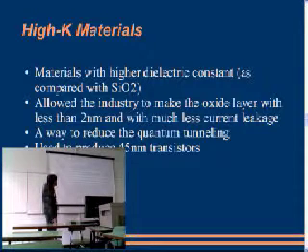The old type of oxide, silicon oxide, doesn't work well at a length of 2 nanometers. When it gets too thin, we have an effect called quantum tunneling in a significant amount.